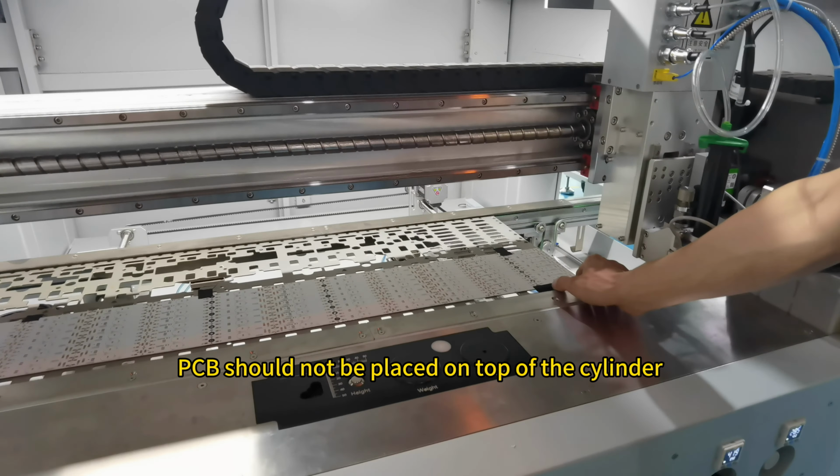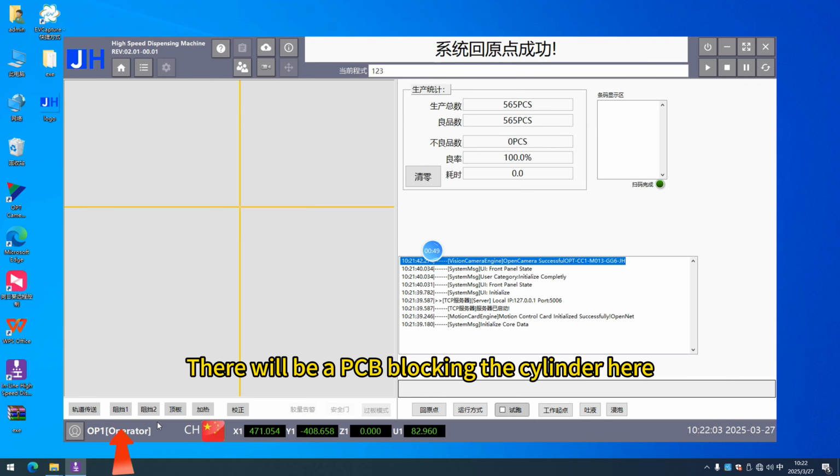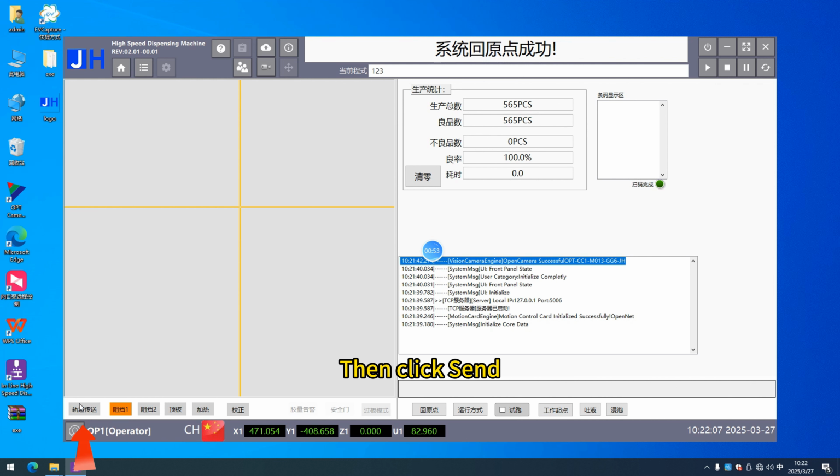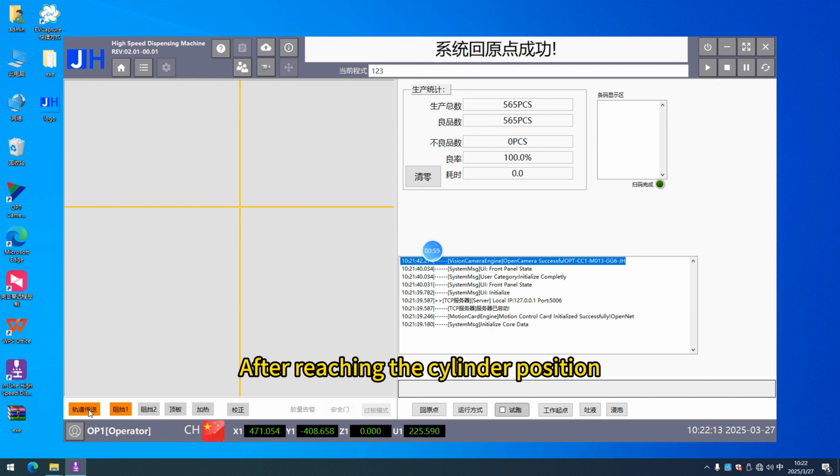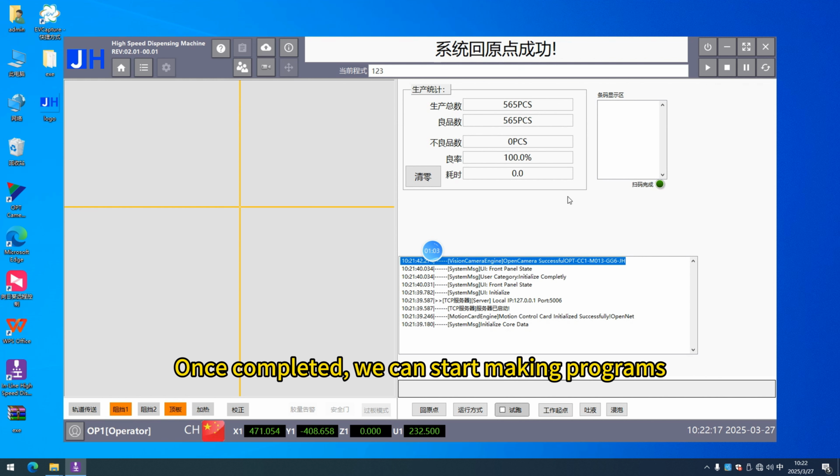The PCB should not be placed on top of the cylinder. There will be a cylinder here blocking the PCB. Click to open, then click send. Wait for the PCB to reach the blocking cylinder position. After reaching the cylinder position, click on PCB to lift up. Once completed, we can start making programs.